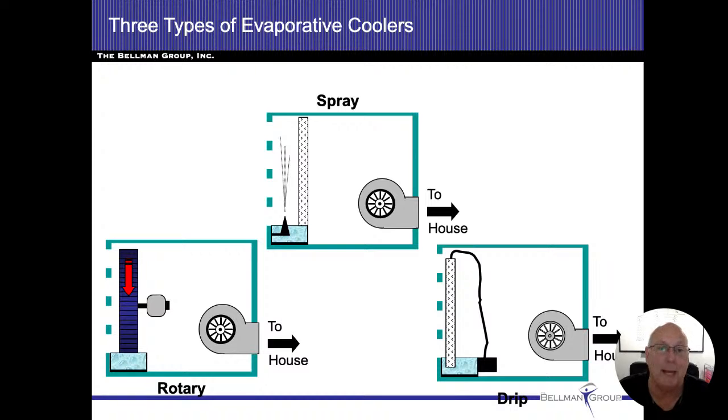And the same rules of science still apply. If I'm going from a liquid to a gas, I have to absorb BTUs. So as I blow moisture into a room and something gets wet, that moisture, as it changes to a gas, is going to absorb the heat of the items that it's touching. Those items will be cool, and then the rest of the house is actually going to be cool.